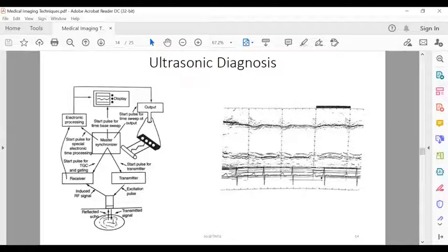The midline echoes from both sides of the head are displayed on the oscilloscope simultaneously, and one side gives the upward deflection of the beam and the other side gives the downward deflection. If these two deflections line up, then the distances from the midline to each side of the head are equal. And if they are non-aligned, then the possibility of a tumor or some disorder may exist.